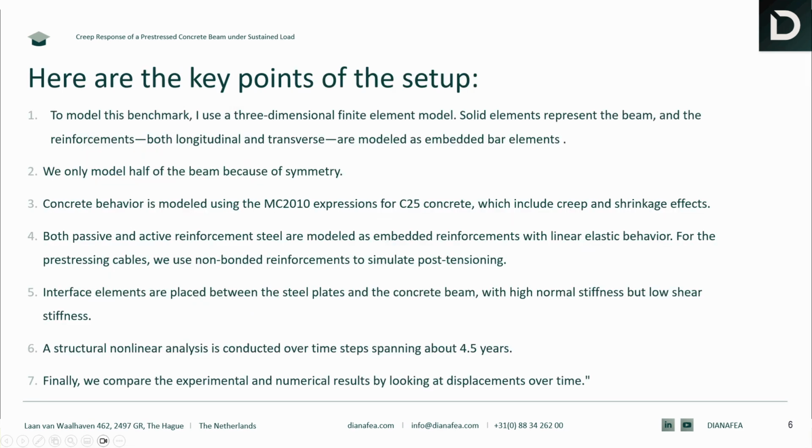To model this benchmark, I use a three-dimensional finite element model. Solid elements are used for modeling the beam and the reinforcement is modeled as embedded bar elements. I only modeled half of the beam because of the symmetry. The concrete behavior is modeled using the MC 2010 and the C25 for the concrete. I also consider the creep and shrinkage effect for the concrete.